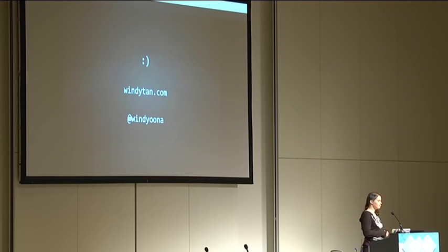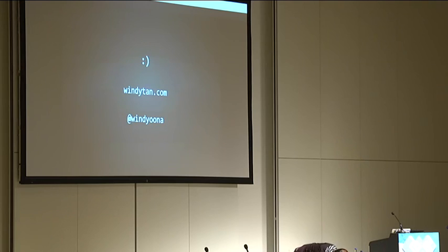Yeah, so the internet wants to know if there is any open hardware radio receiver you can recommend for tinkering at home. Yeah, the RTL SDR is a very good piece of hardware to start with. I think I have one of those with me right now, the one that I showed with the Hello Kitty tin around it. I'm using the tin to attenuate any local interference.